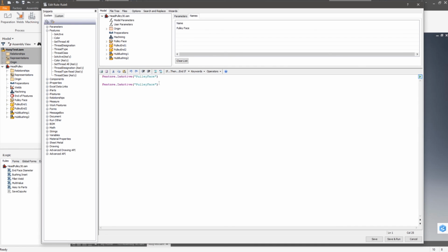And this is where underscores came in. That's why initially it was important to have underscores, because you're filling that blank space with a character. So you can easily work within the iLogic editor. That's where the enhancement comes from. It's not a performance thing. It doesn't slow you down in terms of what Inventor expects. It's just a better way of working within the editor.